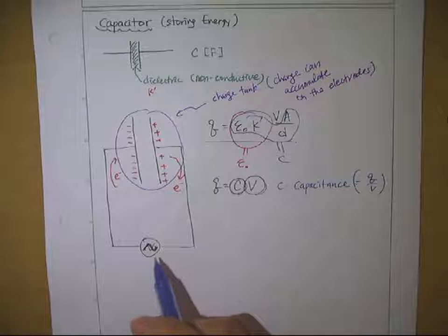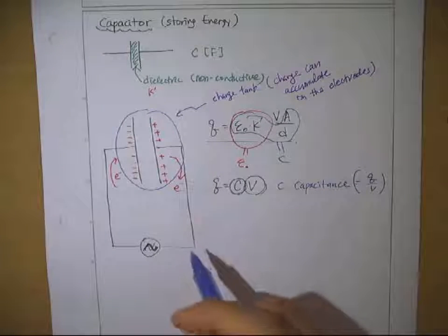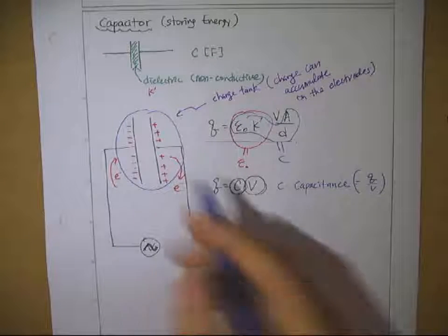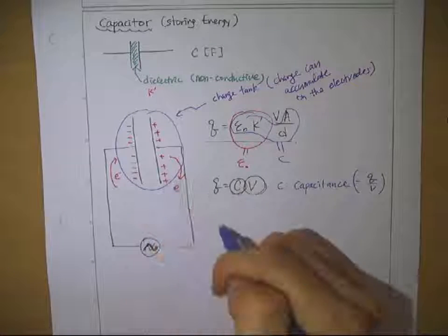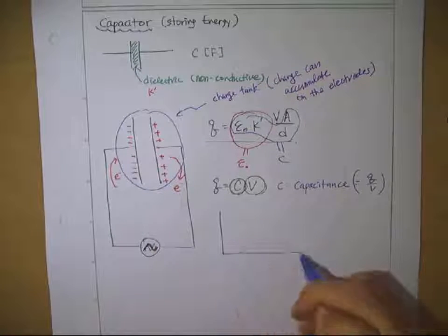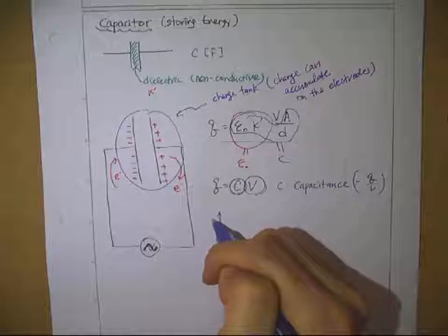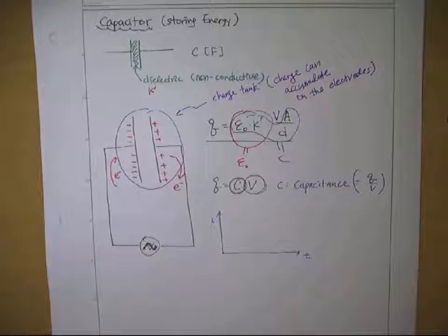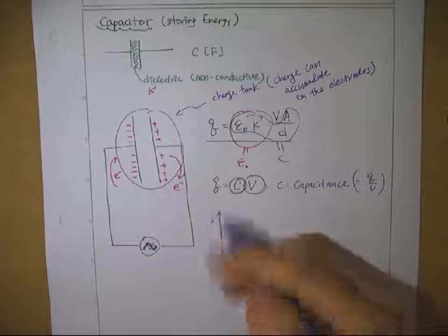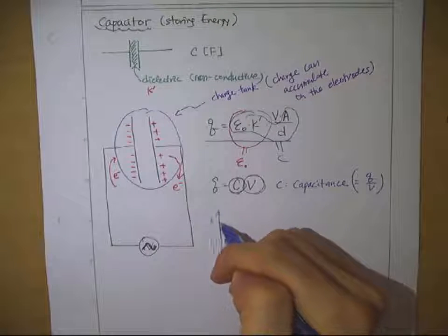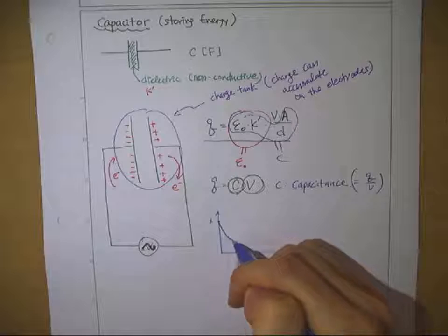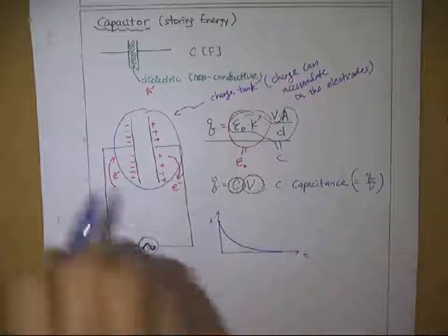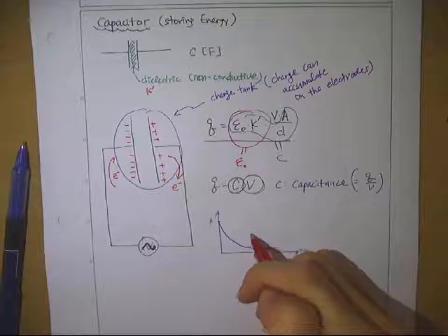So when you apply the DC voltage to this capacitor, in general the current changes with time. At first, because the charge has to be stored, you have a high current for that time, but as time goes by it dies out. So this is called the charging current.